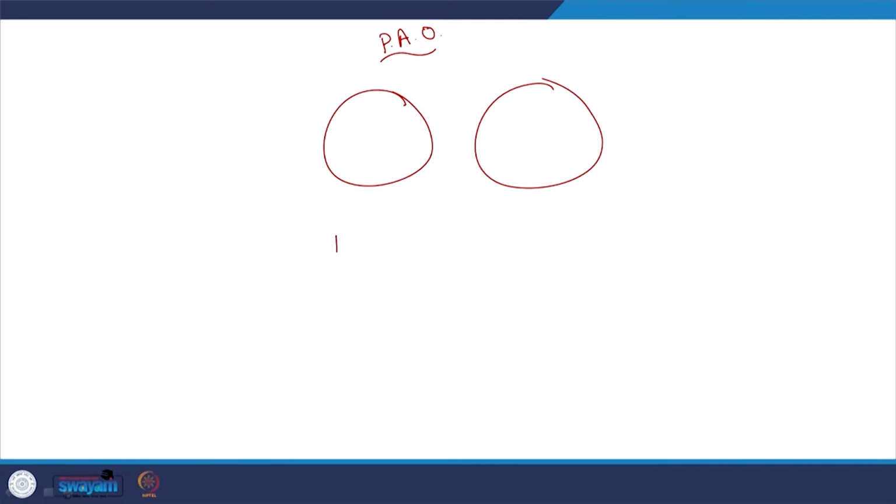So, one is anaerobic conditions, meaning we do not have any electron acceptors here, right, not anoxic, not aerobic. Aerobic, oxygen is the electron acceptor. In the anoxic case, we typically have NO3- as the electron acceptor. In anaerobic, we do not have oxygen or NO3-. And the next we will have aerobic conditions.